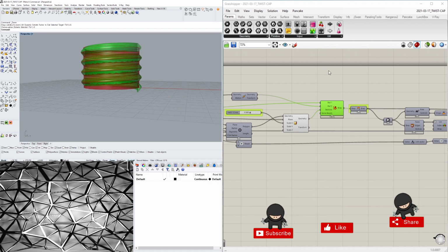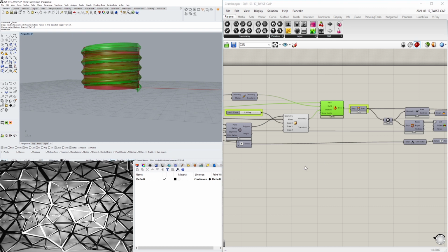And I've already done that. And if you can close it, it'll be impossible to open back up, especially when you have layer lines that kind of create a bit of a tightness that it's strange to even describe. So what I would say is make the tolerance, play around with the tolerance to see what's best for you. But for me, what worked was 0.3. It made it easy enough to open and close, not too tight, not too loose.